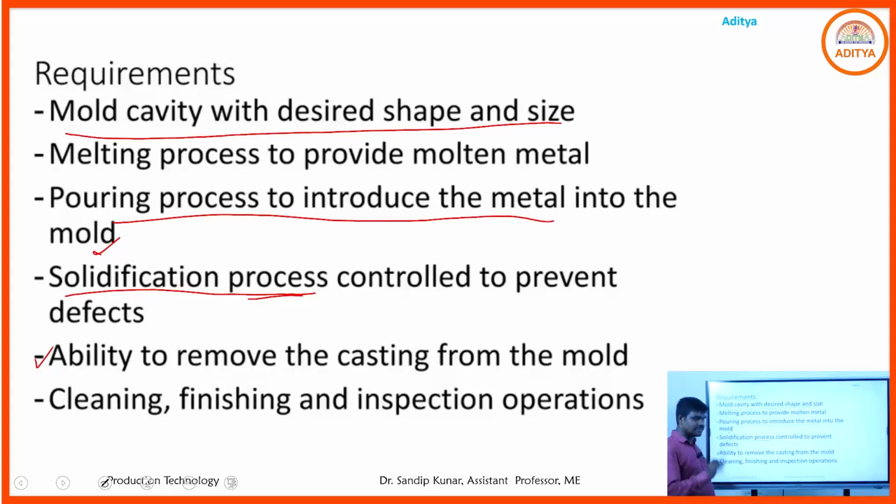After solidification, we break the molding box, meaning we separate the cope and drag frame. After separation, we remove the molding materials, such as sand and other additives. After removing those, we remove the pattern. After removal of the pattern, finally we get the desired shape as a replica of the pattern.